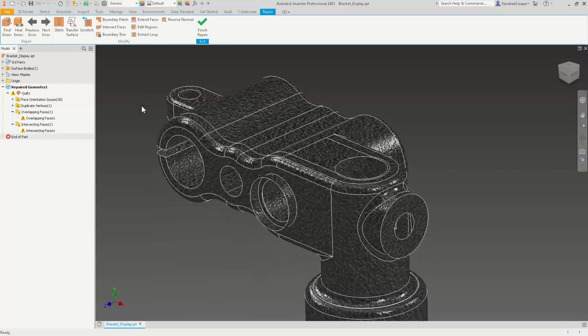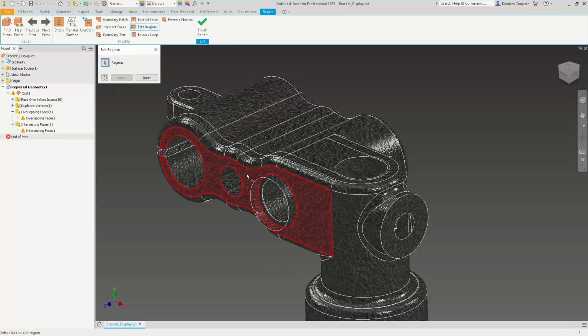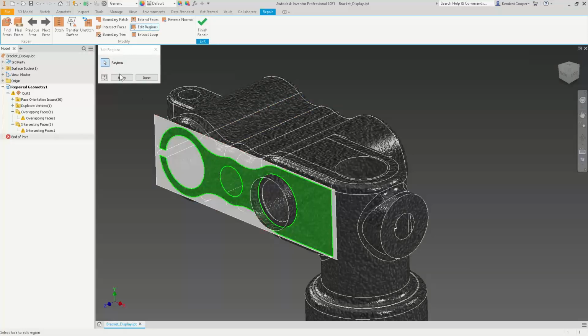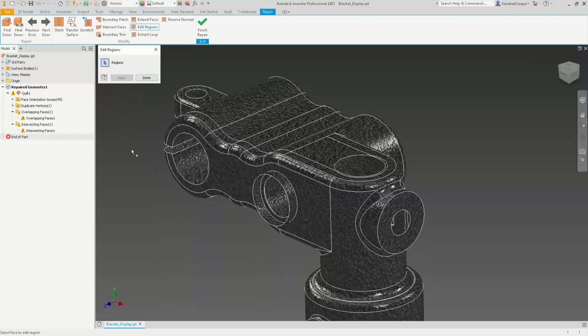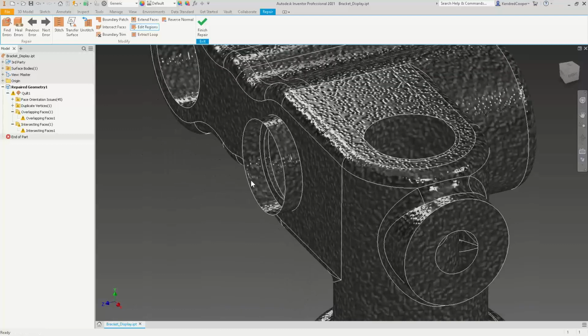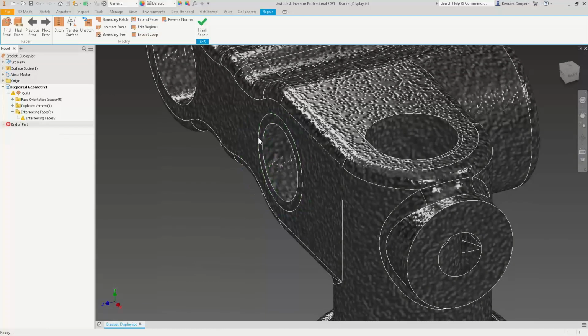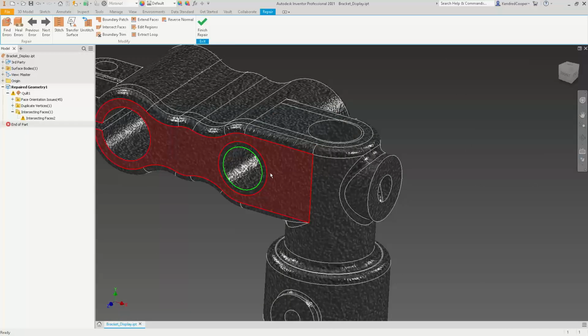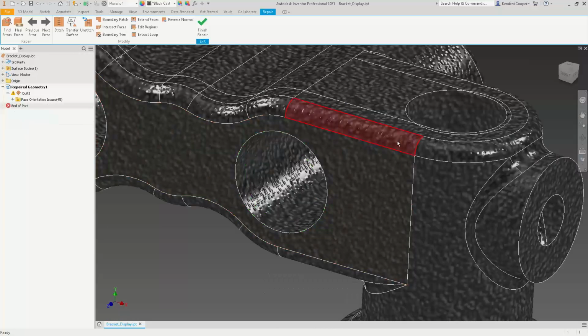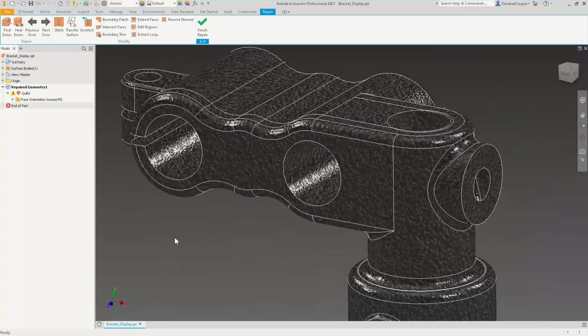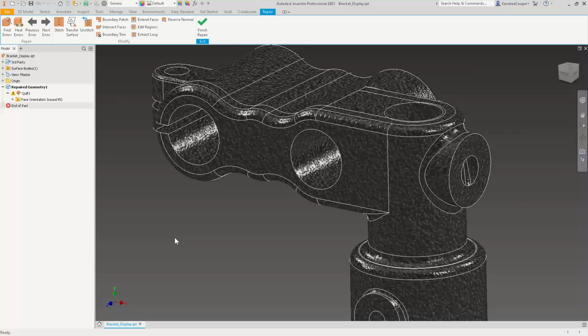If you're looking at things like extending the faces or edit the regions, they still work the same way as what you have in the construction environment to fill in those holes. You can still come in and just select a surface and delete it. That'll simplify, again, the history because there isn't any. You're building this model. Once you get everything fixed, then when you're done, you're going to run a final stitch, and it's going to unify everything back together as one quilt.